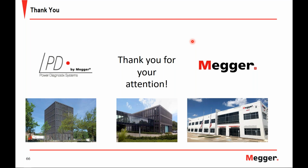Continuously looking at how the PD pattern develops with increase of the test voltage can provide you different phase resolved PD pattern properties, which then all point to a specific partial discharge activity. So message number 1: slowly ramp up the test voltage and monitor accurately what happens with the phase resolved PD patterns. This way you can reveal different kinds of PD activities which tend to incept at different test voltages.